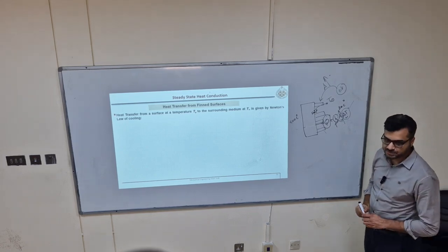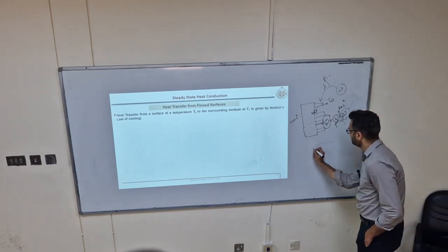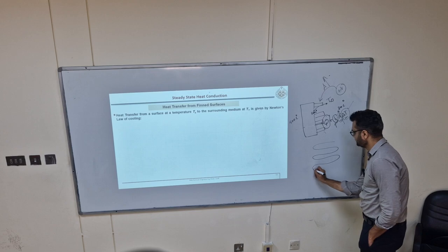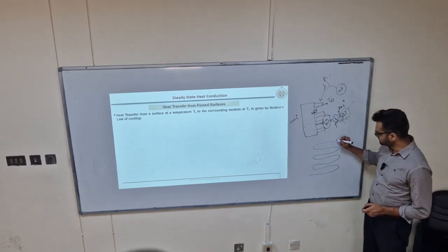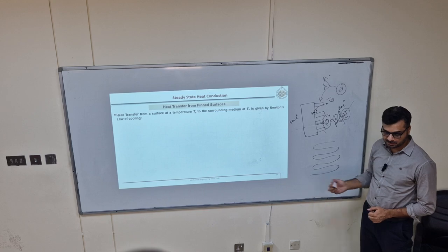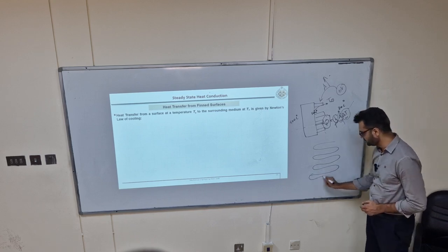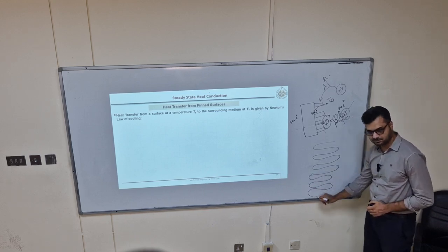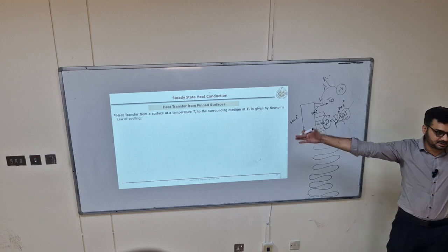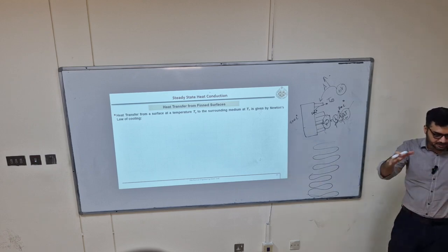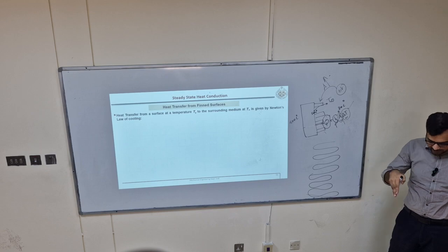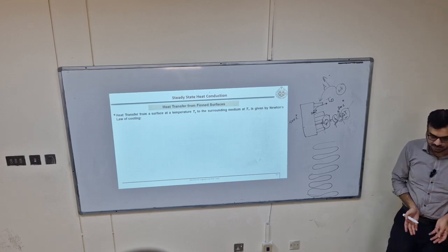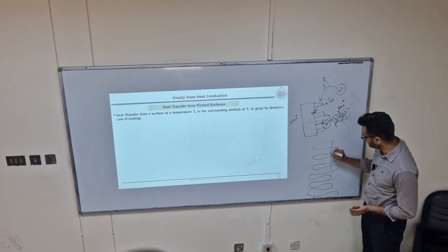Like in the AC, you see in that AC, there is a pipe like this one, right? But on this pipe, to increase the area, there are two ways. Keep on increasing this length. Yeah, it will be much larger, but you have a limitation about the volume. Your car radiator has to be fixed in a very small volume. So you increase the area like this.